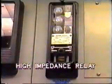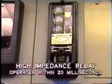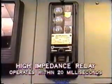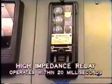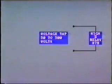The lighter bus faults will be cleared by the high impedance relay, and this operates within 20 milliseconds, that's about 1.5 cycles. This is also extremely fast operation. The setting of the high impedance relay is achieved by selecting the correct voltage tap, usually between 50 volts up to 500 volts.